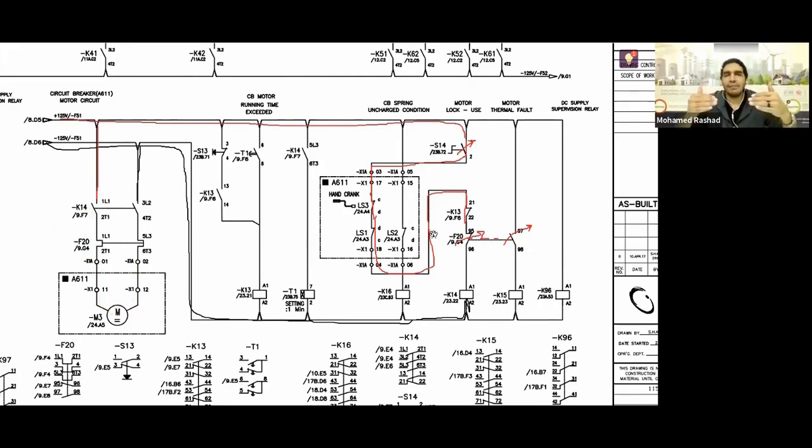You might say, well, what happens when the load decreases? This overload is usually a hand reset or manual reset. So you have to go to the overload itself and do what? You reset it. Otherwise, this contact will remain open permanently, cutting off the power to K14. So why did you use it to activate K15? Because I use K15 as an auxiliary relay for contact multiplication. The word multiplication means, let me explain it to you better.